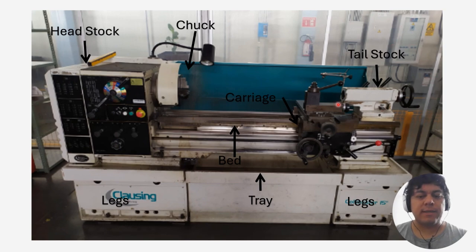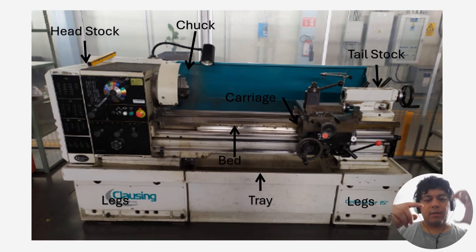And we have the tailstock, which is the other part. Whenever you have a very long material, of course, the longer the material is, the greater the momentum it creates, and therefore the bending force is going to be greater the farther you are from the chuck. So you want another part to be holding the end part. You have the first part here on the chuck, and the tailstock is going to hold it with a pin.